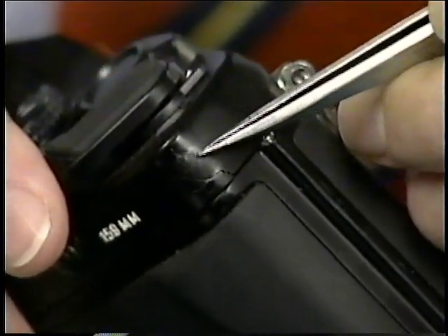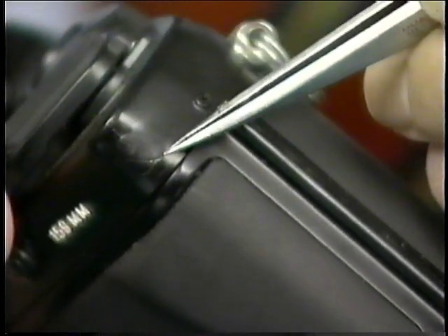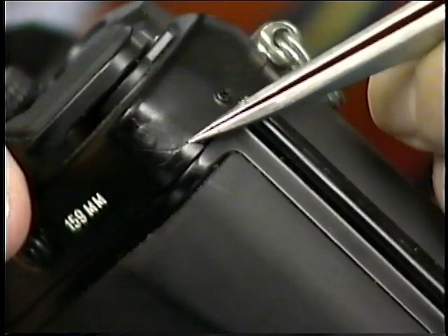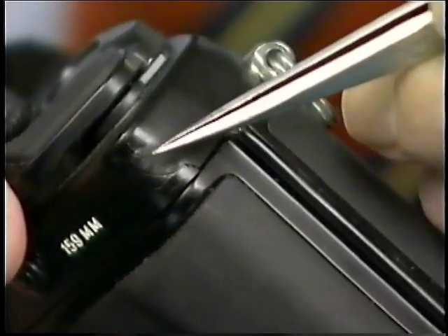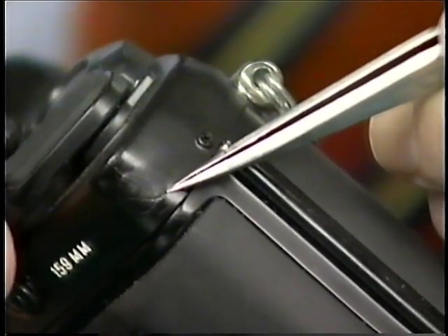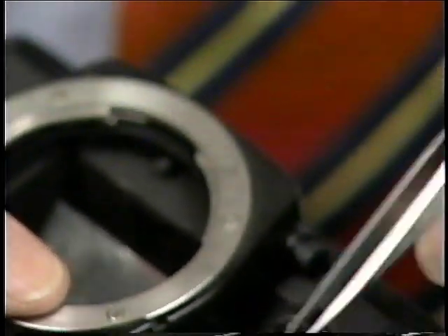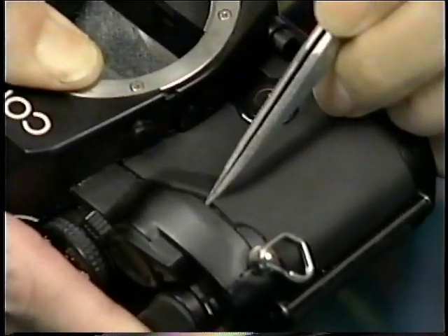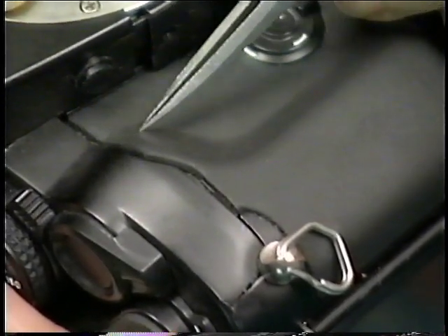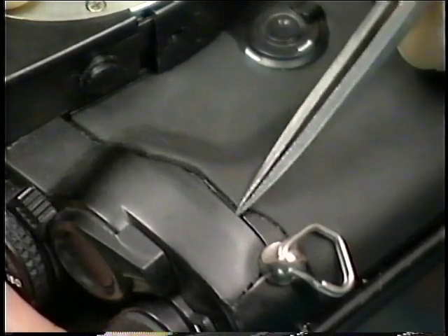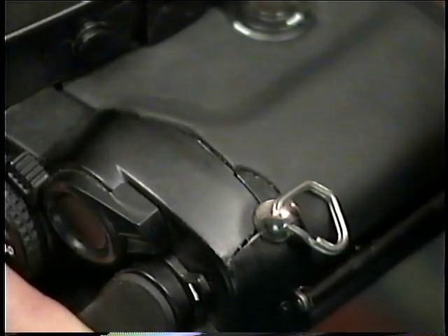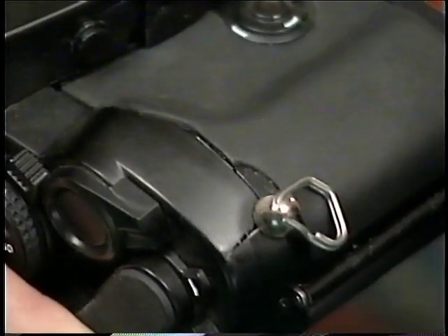Look at the corners, and you can see a significant amount of impact on this corner, also a small corner crack. That doesn't look too bad, but in order to crack a plastic cover like this in such a fashion, this had to take a very severe hit. Also, look along the edges between the covers and the body for open seams. You'll see this cover has actually been lifted and torn away from its mountings, and there's a wide open seam there along with yet another crack here by the strap lug. This is another indication of very severe impact damage.